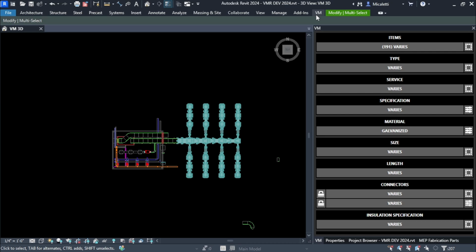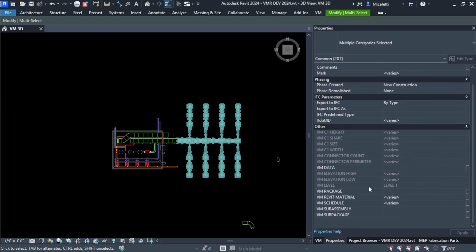And it doesn't matter what you're using, Trimble, Topcon, whatever. They'll have documentation on the order of the CSV. Some want XYZ, some want ZYX, northing, southing, easting. But they also allow extra data at the end that you can just push along, and you can literally push along everything in basically any of these parameters, right?